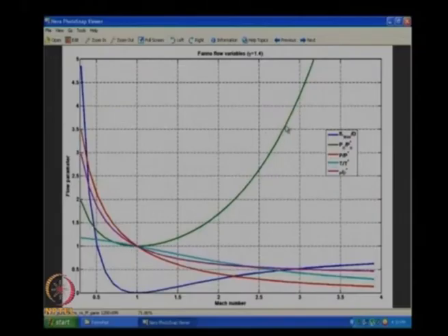If I pick a supersonic condition, I am going to have P naught dropping, in arbitrary units. Let's pick a Mach number of 2.4, where P naught is about 2.5 times P naught star, and by the time it goes to M equal to 1 from 2.4, it drops to P naught star. In the subsonic case, of course, I cannot get an exact equivalent, there is less space, only between 0 and 1 I have values. But what we are seeing is, if I think about a 0.5 Mach number jump, I am going from something like 1.3 to 1 P naught star.